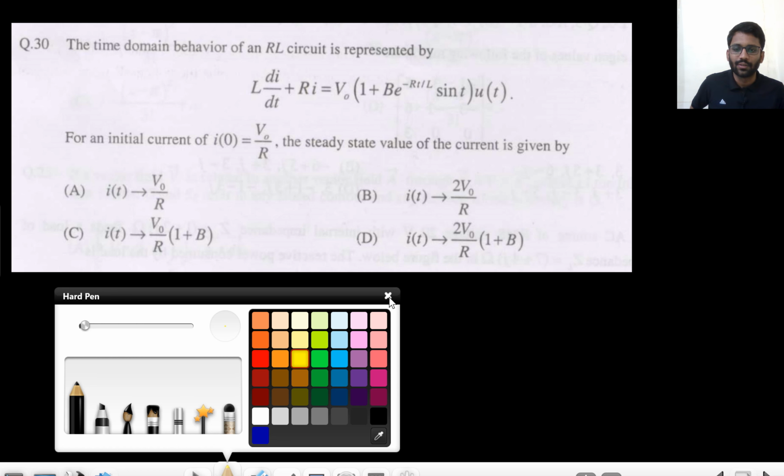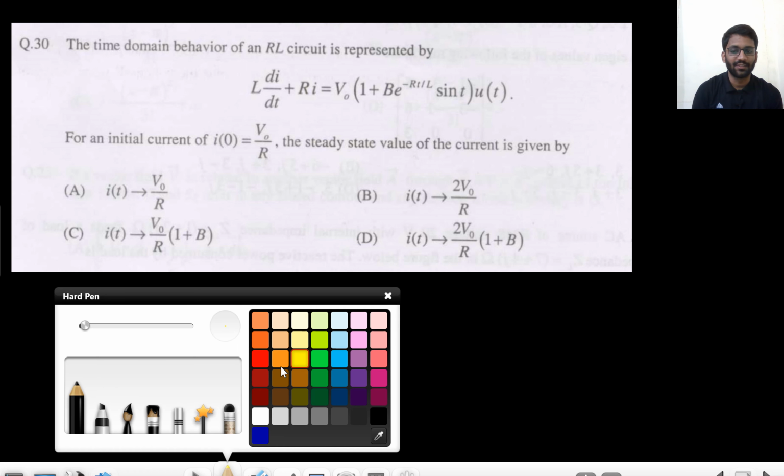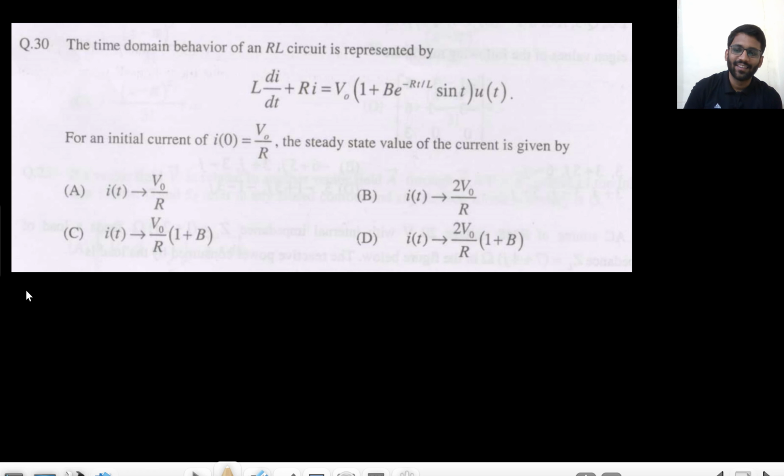This is also a very good question. So this will also give an insight into why I teach too deep. Okay. So L di by dt plus IR equals some voltage. Can you think of the circuit? What will be this circuit? Voltage into current into resistance plus L di by dt. What are they applying here? Current is the same everywhere. That means they are applying KVL. And this is a series RL circuit.